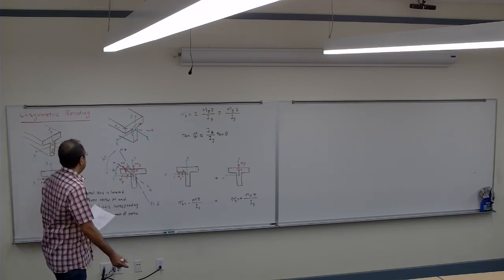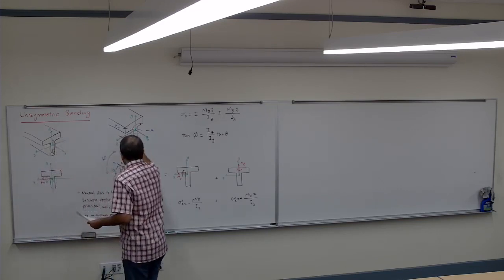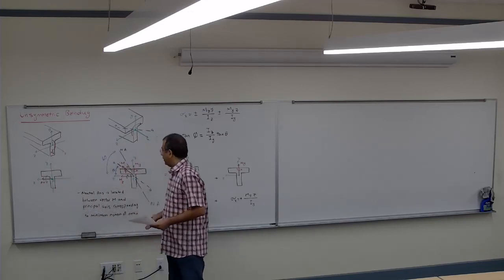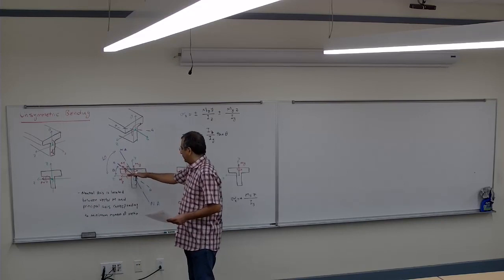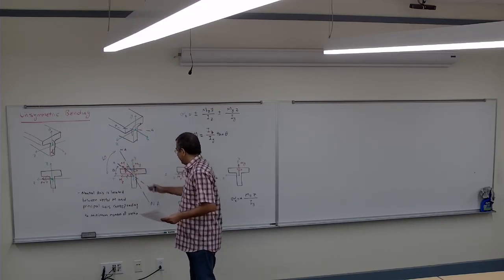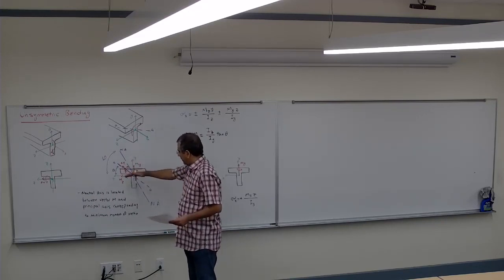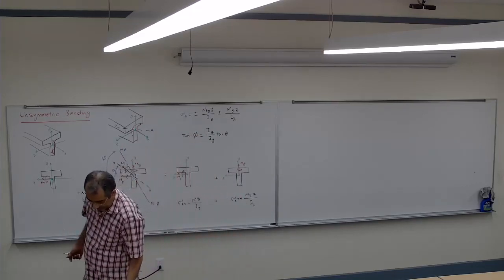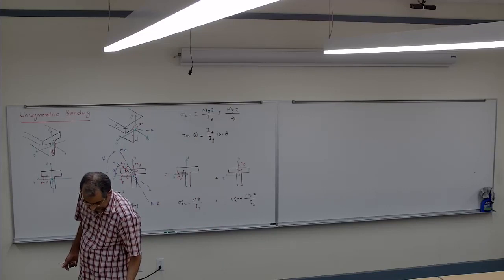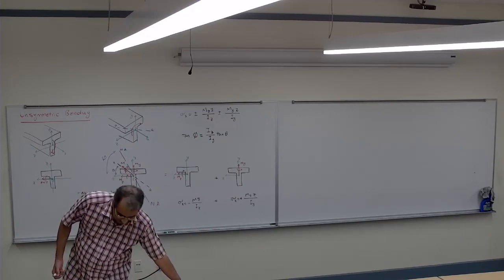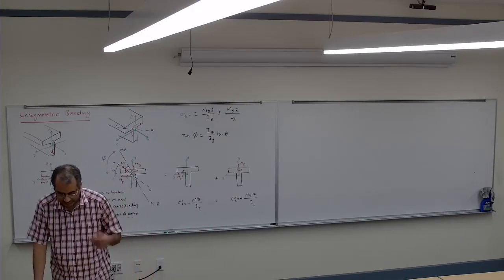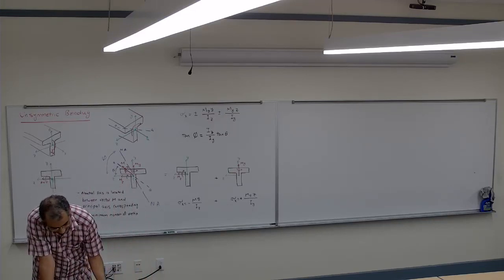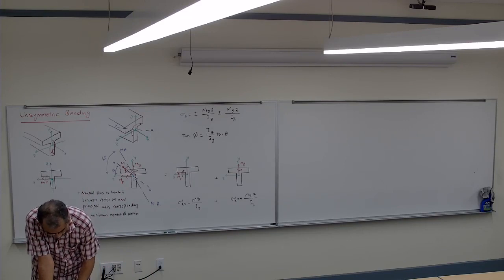So for example, in this case, the minimum moment of inertia is about the y, so the neutral axis is going to be between M and y. If the minimum moment of inertia was about z, the neutral axis would be between M and the z. So this is the case if we have a moment that's unsymmetrical, that's not about either of the axes.